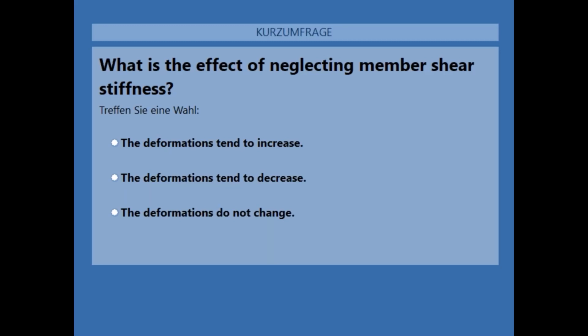Okay, the answer would be that the deformations tend to decrease. Because the shear stiffness factor, when you deactivate it, goes to infinity. So it makes the system harder, I would say. So yeah, the answer would be that deformations tend to decrease.